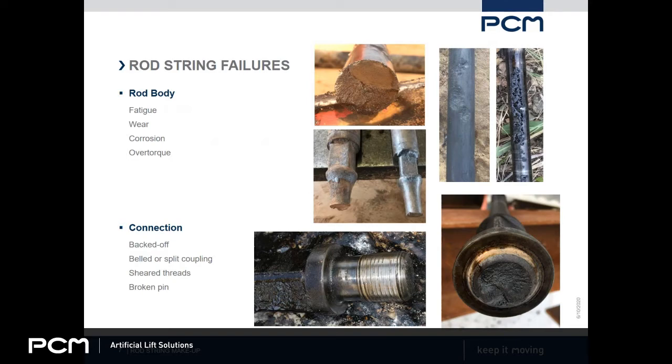But there are some companies that run with packers, which allows them to actually continue running when there's a hole in the tubing. And then you can end up going to the point where the rods eventually wear and break because of wear. But that's much less common.